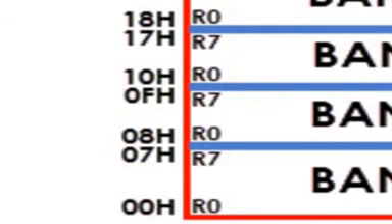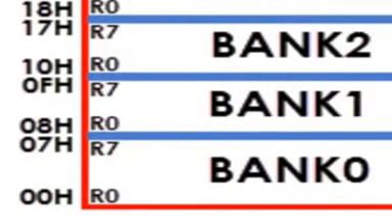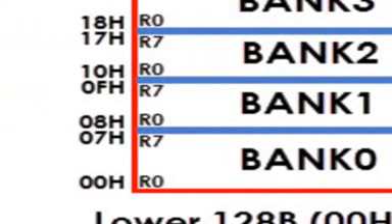Then if I want to store some other value, again it will increment from 8 to 9, and the other value will be stored on 09th location, that is R1. And that is of 8-bit size. I said stack pointer is of 8-bit size. By this I can say that this bank 1 is generally used for stack pointer operations, to store the values of stack pointer operations.